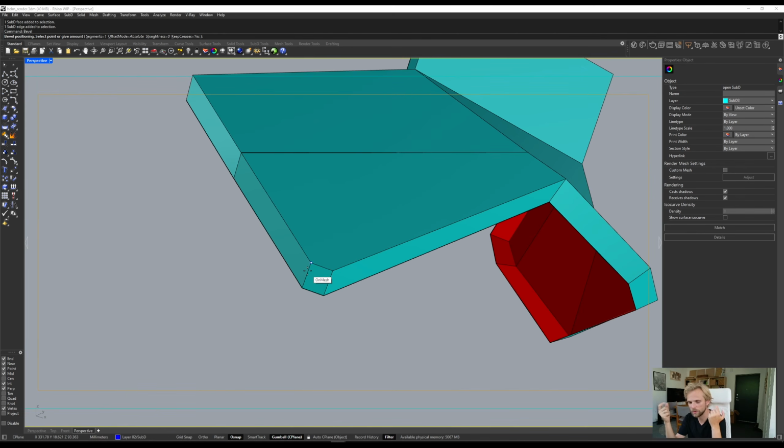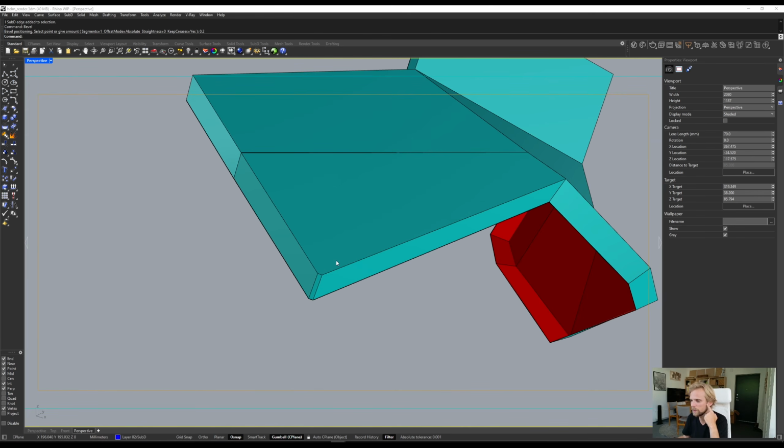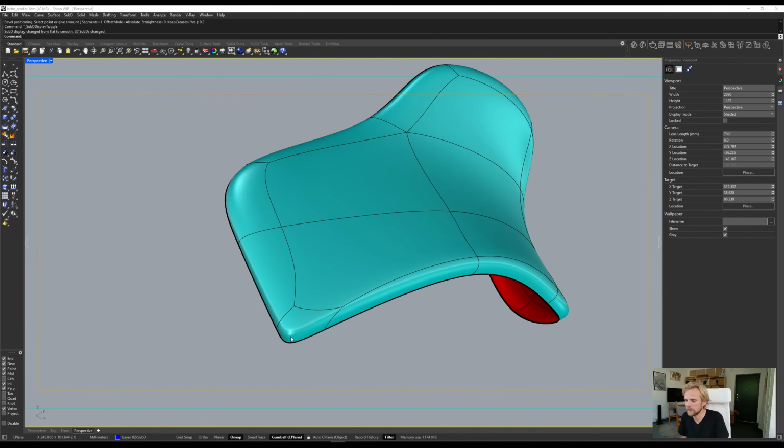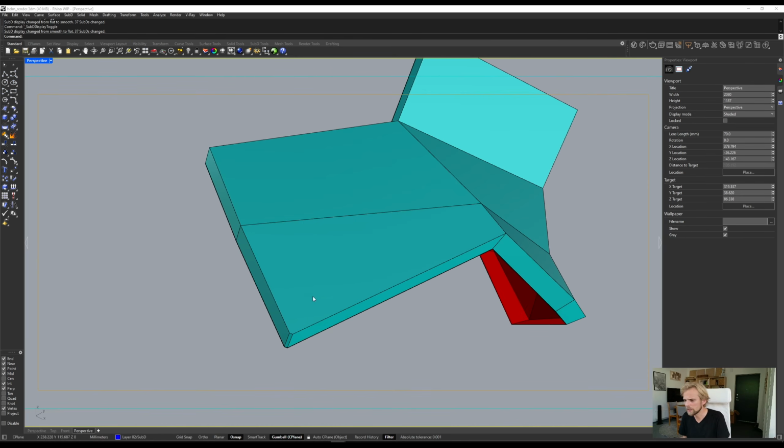So extrusion was 2, so let's go for 0.2, 10 times smaller, 0.2 for the bevel. And thus it creates this little corner here. Now if I press tab, you can see that the corner is being held much better compared to its friend here that didn't receive the bevel, right? So that's how it works.